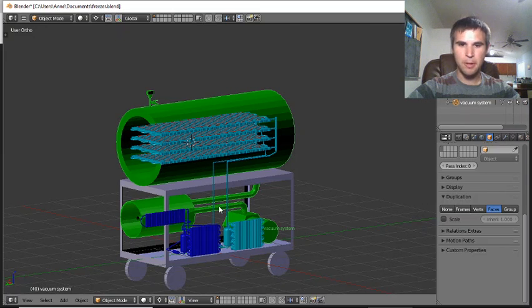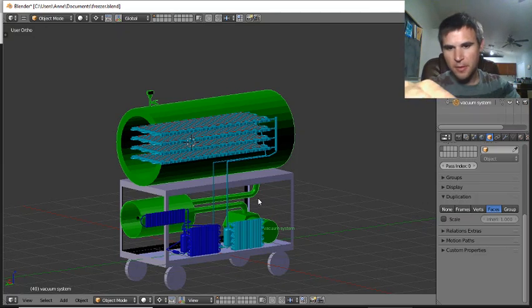We have to have some amount of length because the vacuum has to pull through the cold trap before it gets to the chamber, so that it protects the vacuum. So we're going to have that, but the pressure won't all pull down equally. The piping closest to the vacuum pump will see a way deeper vacuum than the rest of the system, and it's just how fast can it pull material through all of that.